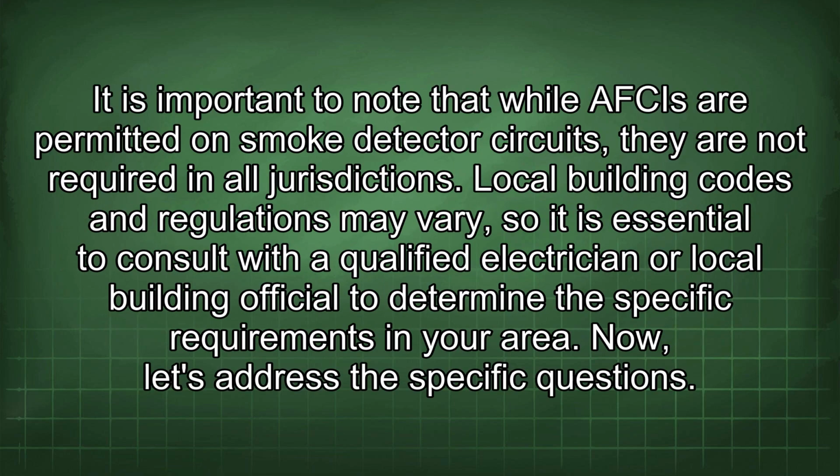It is important to note that while AFCIs are permitted on smoke detector circuits, they are not required in all jurisdictions. Local building codes and regulations may vary, so it is essential to consult with a qualified electrician or local building official to determine the specific requirements in your area. Now let's address the specific questions.